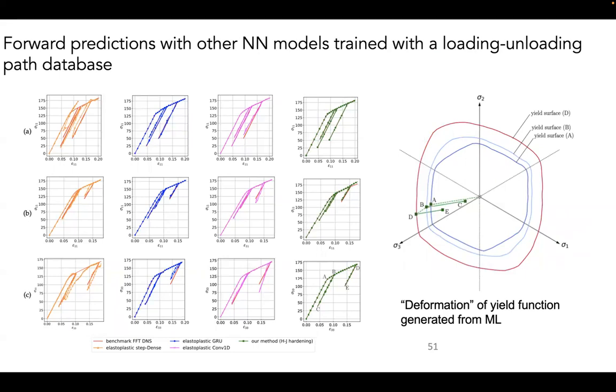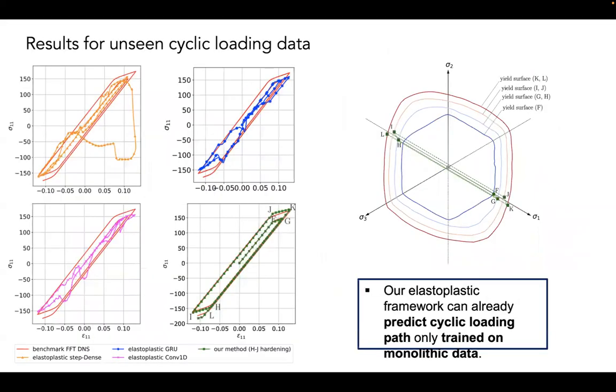Here you can see that the results, compared with the RNN or convolutional 1D, are a little bit more robust, and won't suddenly have this fall-off-the-curve behavior. So why is that? You may still make wrong predictions, but the regularity of the yield surface that you generate prevents you from suddenly getting this. It's really hard to get this. This oscillating pattern is very easy to get in the recurrent neural network, simply because of how the memory is introduced. It's from feeding in the previous time step. So you can see that for monotonic loading, it has no problem.